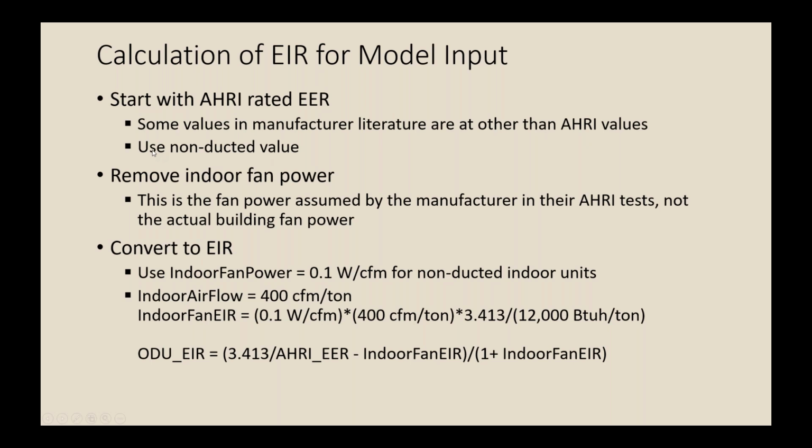Also, AHRI will specify conditions as either non-ducted or ducted. Even though you may be looking at the rating values for the outdoor unit, which doesn't actually ever connect itself to a duct, the AHRI specifies that those would be tested with either ducted or non-ducted indoor units. So when you're getting an EER for use in a model, you want to make sure that the value you're getting is for a non-ducted test. That's something to pay attention to.